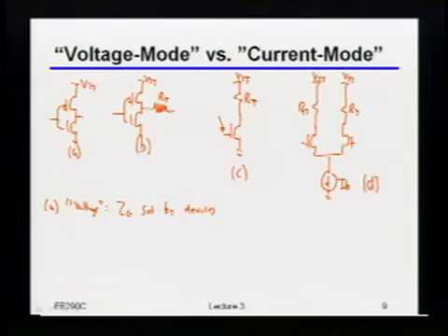But actually, since I didn't show you any sizing or anything like that, you don't actually know if it's really low. Because I could have made them small, and then it could actually be high compared to the transmission line. So it's really just set by the devices. Right? Okay. What's the other sort of thing that's implied by this particular driver? Just in terms of the list of 3 different things that I mentioned in the previous slide. There we go. The swing is set by the voltage, right? The swing here is set by VTT, right?